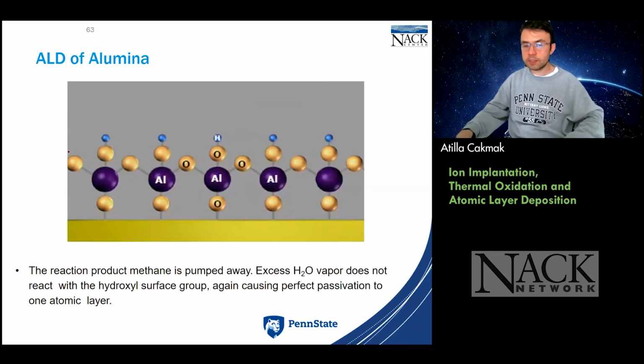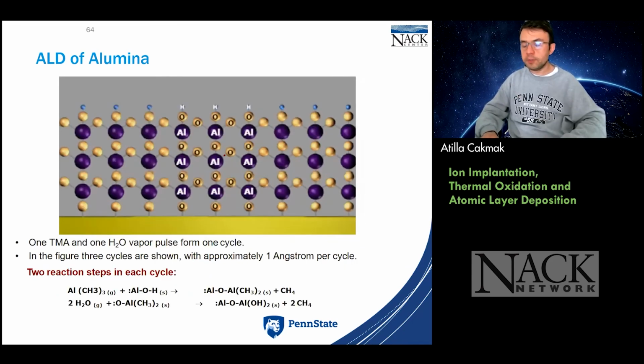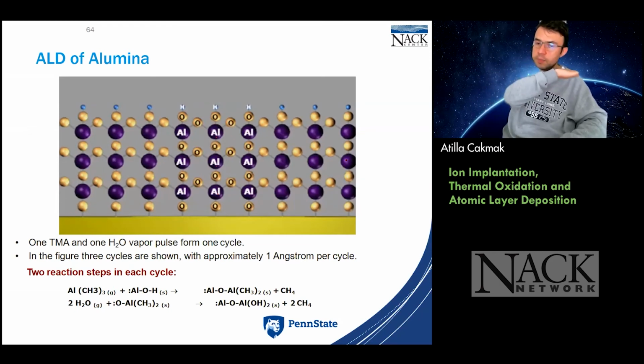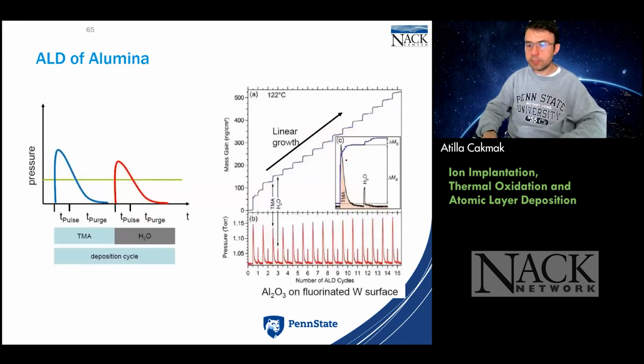So as soon as this is ending, we go back to where we started. Remember this? We have hydrogen here, we have oxygen at the bottom. So that's what we started with, and that's what we end up with after one cycle. So this is one cycle here, and if we do a couple of cycles, we will grow that many. So we've just done 1, 2, 3 cycles, and we just achieved this many on the surface. So you see now how controllable this is, right? And how conformal this can be. What I mean is the uniformity is absolute. Everywhere is now 3 aluminum. That's wonderful.